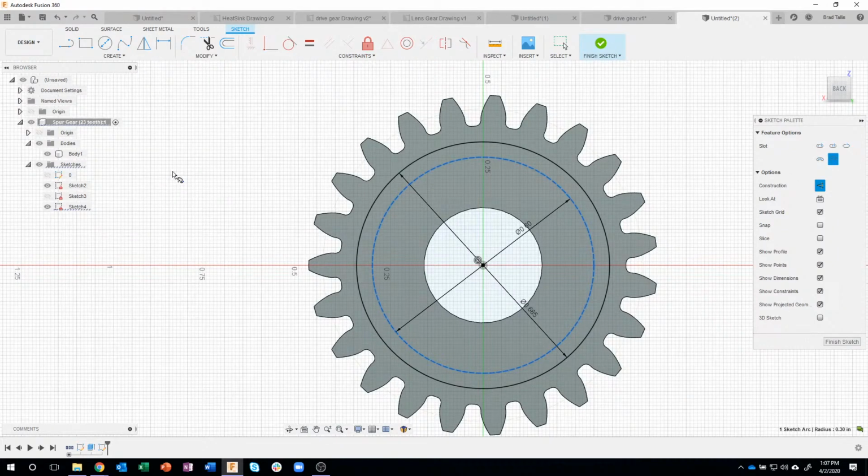Okay. So the first thing it's asking for is select center point of arc. So I'm going to click here. And then I'm going to go ahead and click somewhere on this circle there. And then somewhere over here. And then finally, when I move, you can see what's happening. Okay. Well, I'm actually going to click on that circle. And I just created this curved slot. Now, I didn't do any dimensions. It didn't really ask for any dimensions. It was all just clicking around.